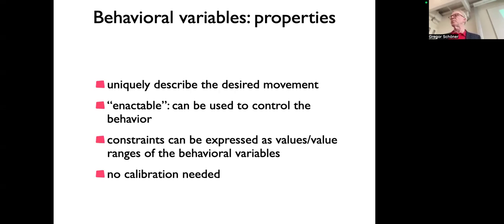So in practice, in terms of control, what all of these robot vehicles do is they have servo motors. There's nothing better than servo motors. Servo motors have some internal sensor, of different kinds, that estimates their rotation rate or even the position on the axle. This can be a little disk that has some encoding where you count how many holes there are, with some sensor for that, or other techniques. And they have a control circuit. I'll discuss a little bit of control in the second part of the course for robot arms. So the voltage sent to the motor is tuned depending on the rotation rate or the position of the motor axle, which then achieves really a desired speed or position.